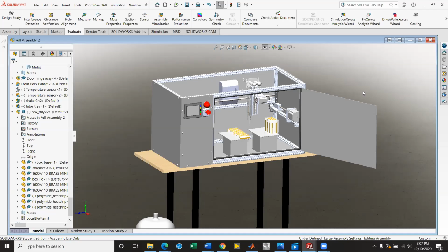You can use somebody else's system, but now you're stuck using 80/20 and their T-slots and all this other stuff. Or you can say, all of our stuff is going to have a 100mm square fixturing, and all of our modules just need that, and they'll drop in and bolt in. Great, done. M6 fasteners with 100mm square. It's the same thing as a VESA 100 TV mount. Now you can use VESA TV mount adapters everywhere. There are other options for modularity, not just 80/20, which you guys are all comfortable with from DML. And I rag on 80/20, I was a DML TA for 6 years. So I'm not ragging on it because it's not useful. I'm ragging on it because it's not useful here.